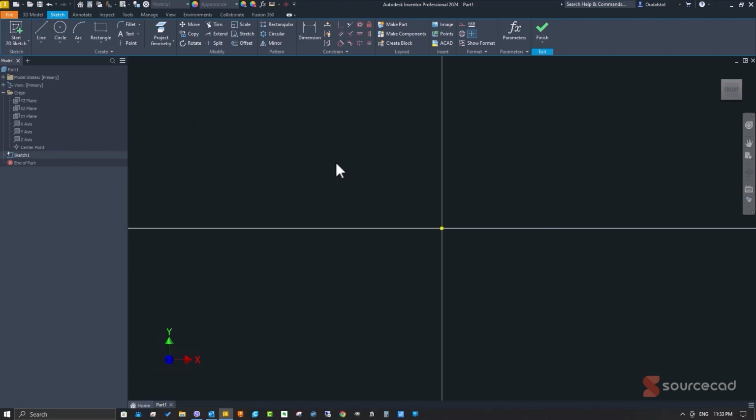This has a point right here, the origin point. Should you find yourself in a situation where it's not here, I'm going to delete it on purpose, it is very useful because you want to tie your sketch to something. We want to go for something called fully constrained. So should you find that I deleted it, I can click this project geometry and click it out again so that I have access to it. Just a quick little tip so we don't fall off right off the bat.